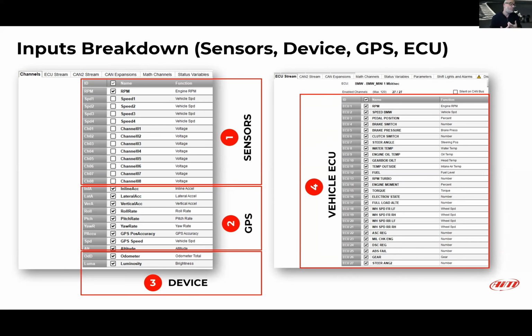So I have all of my channel ports in use on my car. I will show you that in just a minute so you can see exactly what I'm talking about. But each of the ones on my car is mapped to a different area. I have one channel mapped to a sensor which is plugged into engine temperature, one sensor mapped to oil pressure, another sensor plugged into brake pressure for the front, another one plugged into brake pressure for the rear. That allows me to do bias. Don't worry, I'll show you that as well. And so these are all different sensors that you configure in your vehicle. This is fantastic and very useful in terms of being able to set up your overall car.